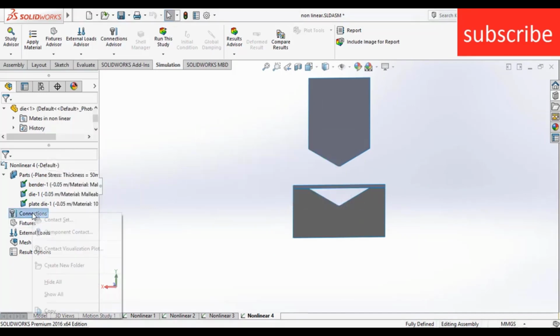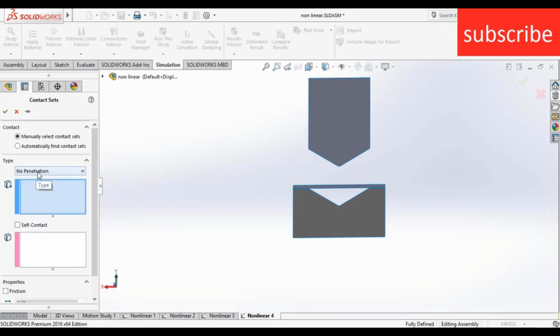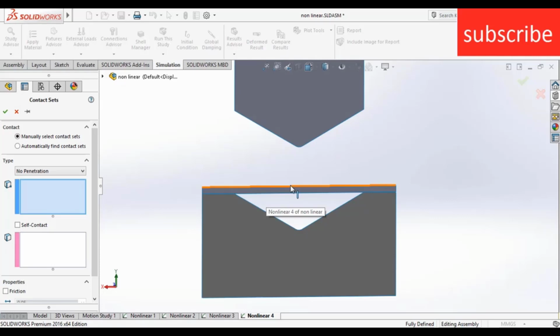click delete. Now right click on collections, click on contact set. Make sure you select no penetration. If I don't click on no penetration, what will happen? It will penetrate the body. In my case, I am just doing a deformation test, not penetrating anything or removing material. What I just want is deformation, like plate bending or sheet bending, etc. This is what I am doing here.